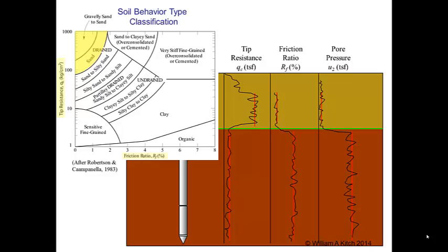indicates. Conversely, clay soils generally have lower frictional resistance and provide less tip resistance during CPT testing. However, due to the significant cohesion of such soils, they stick to the side of the friction sleeve and generate a relatively high friction ratio.